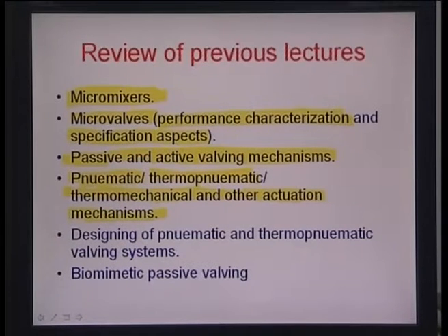So, we also tried designing some of these pneumatic and thermopneumatic valving systems and saw that especially the designs have to be made in a manner which suits the micro scale, and it makes an area ratio between the inlet and the valve seat, so that the amount of force needed for actuating the valve member is small.